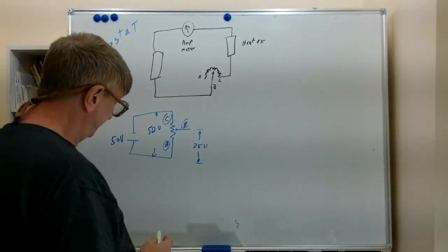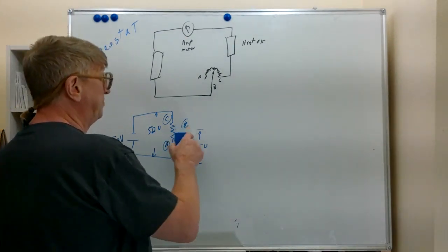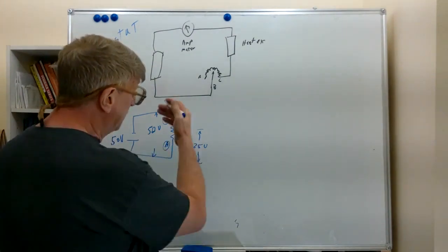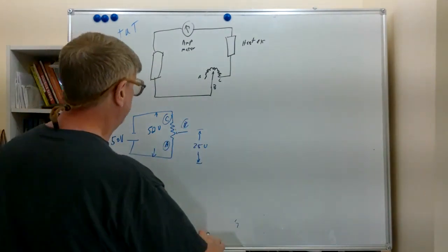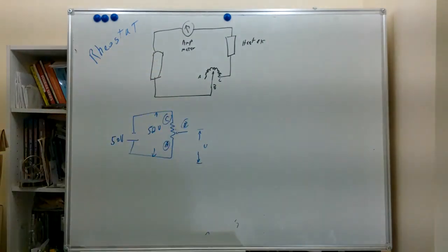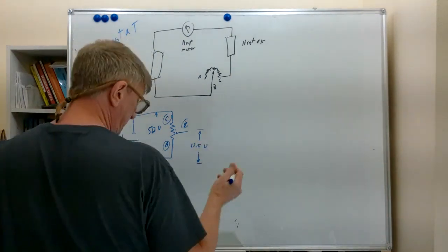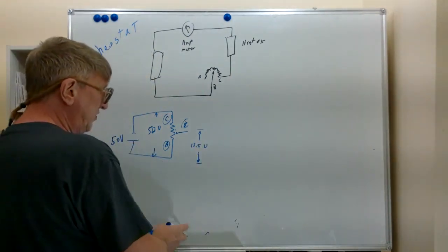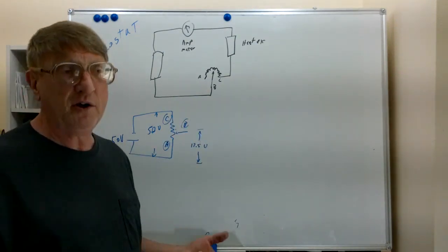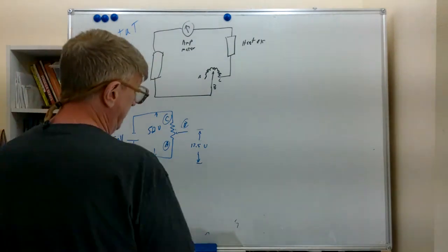And if we have this set down at 25%, and like I said before, we don't see this move, but 25% would get us to about 12.5 volts. So we could use this potentiometer thing, we usually use it to pick off part of an electrical signal, the desired amount we want.